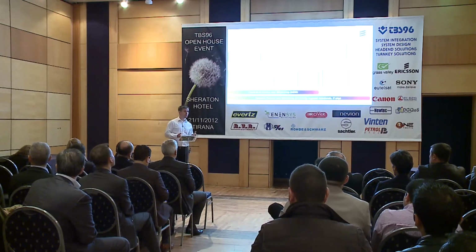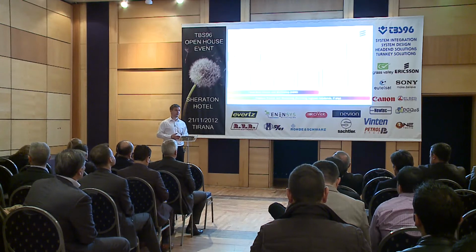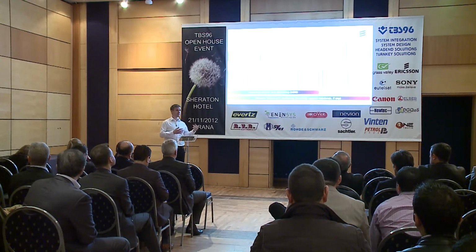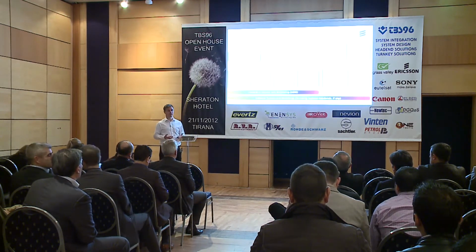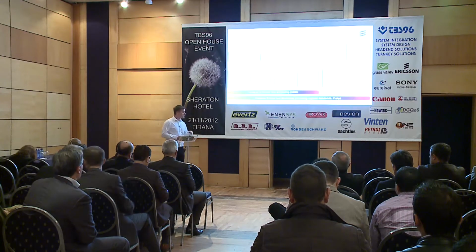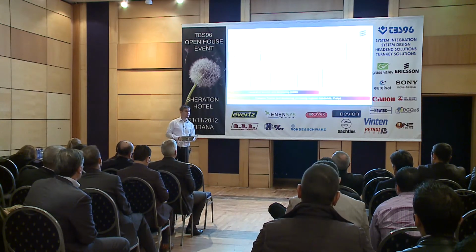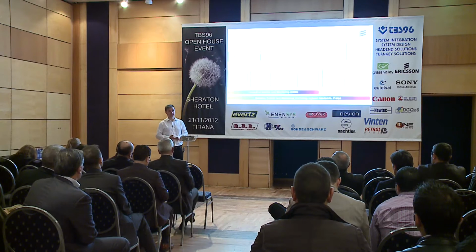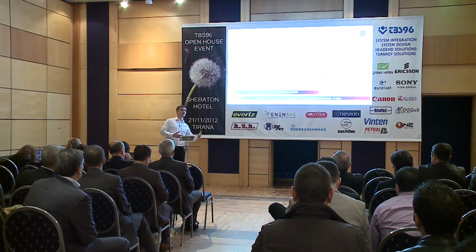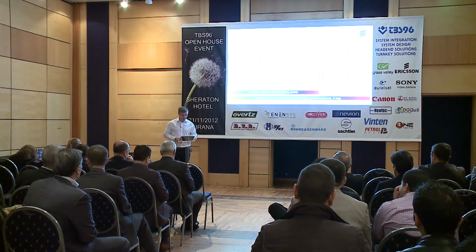So if it's modulated from satellite, the receivers will demodulate it. If it's scrambled, the receiver will descramble it, and it will also then decode it into baseband video and audio. So those services are then fed into the encoders, and encoders is where that's really ex-Tandberg and now Ericsson Television's core competence.